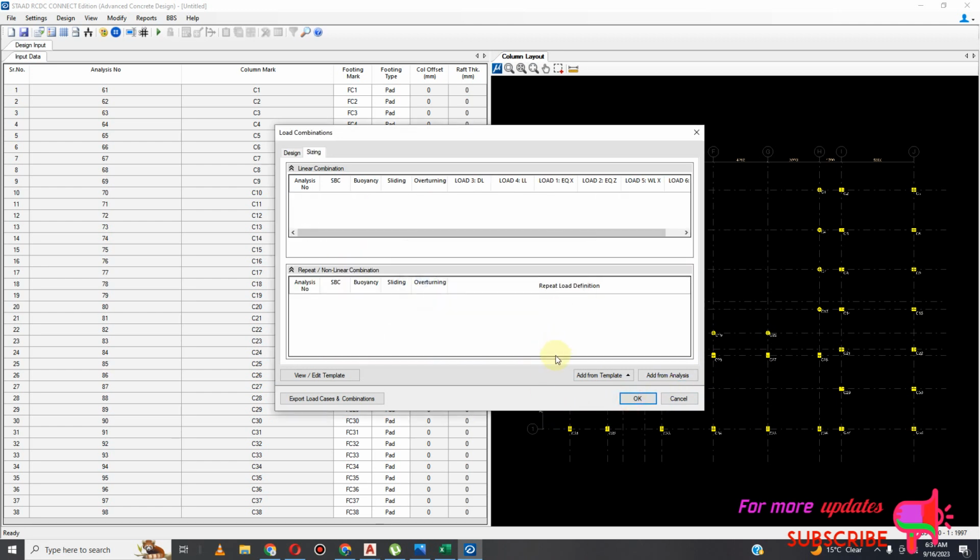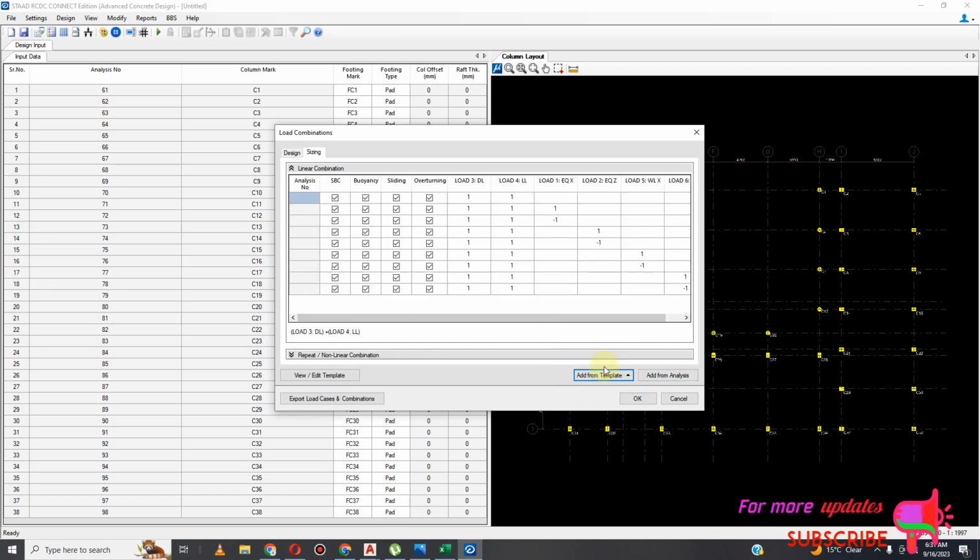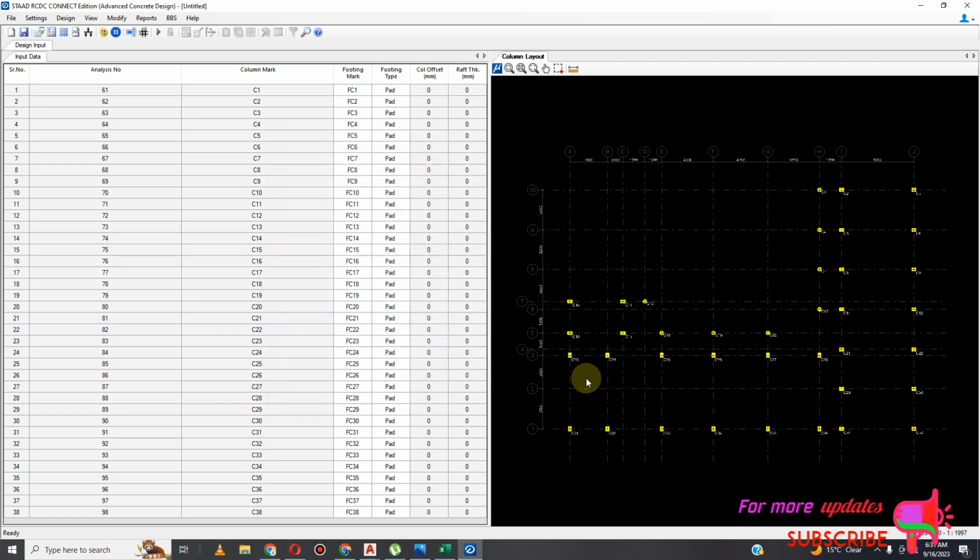And then the sizing factor is definitely 1 from a regular structure. Okay. Sizing factor is basically, remember there is ultimate load and there is factored load, so sizing is just 1, the unfactored load case. Alright, then run the analysis. I've forgotten one important thing, but it's okay.